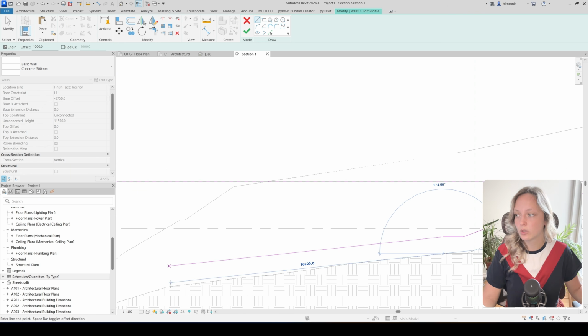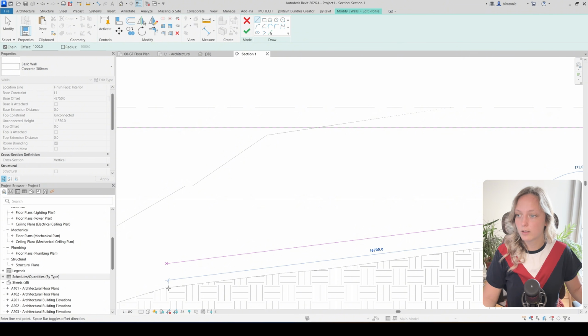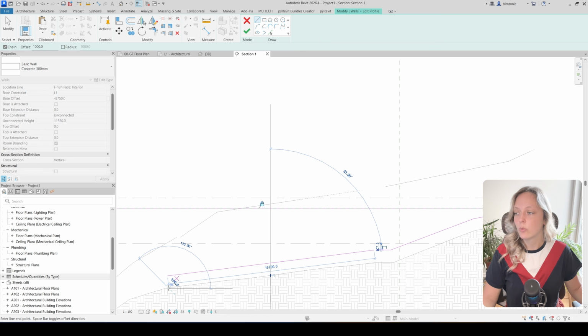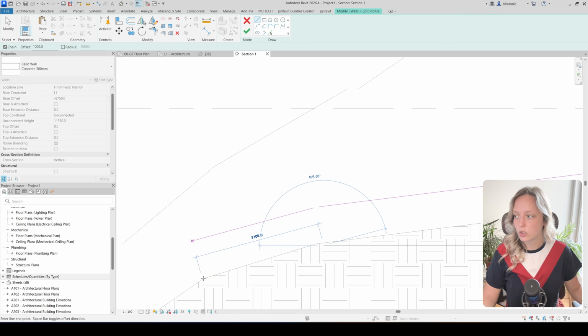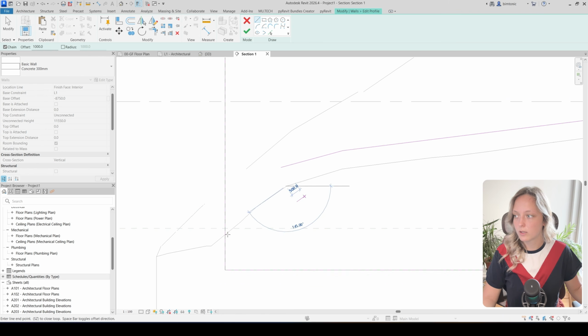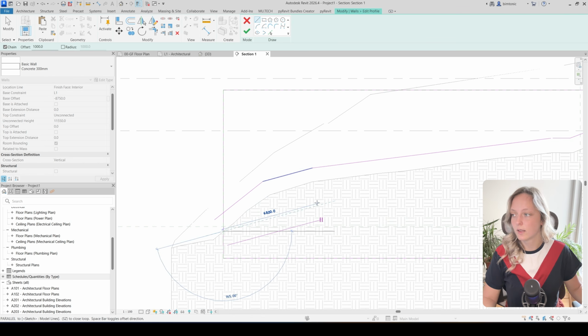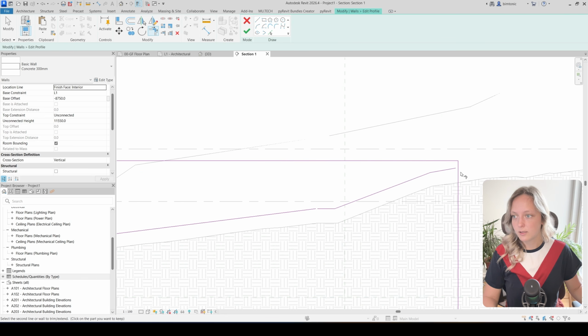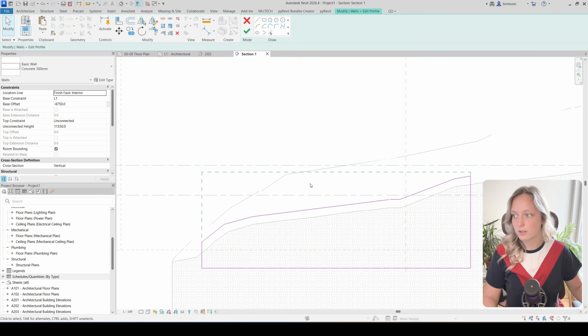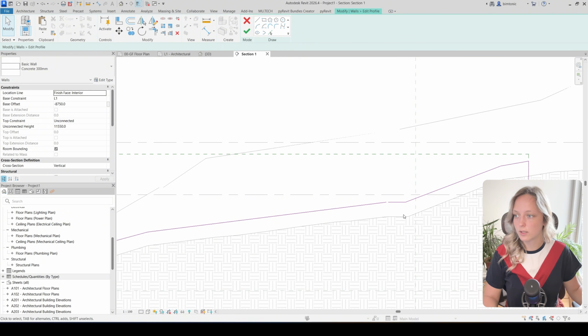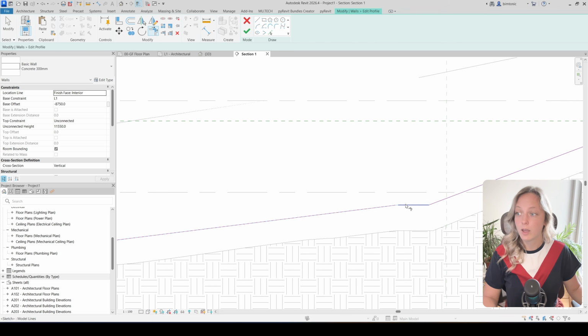It is basically not the same one plane, but what we need is actually to not cut our wall too much. We do need to hold this direction as long as it's possible. We have the very sharp sloping here, so here we actually create these different lines. Now that this is done, I simply trim these edge lines and I delete the upper line. And this is how it looks on the upper line of the terrain.